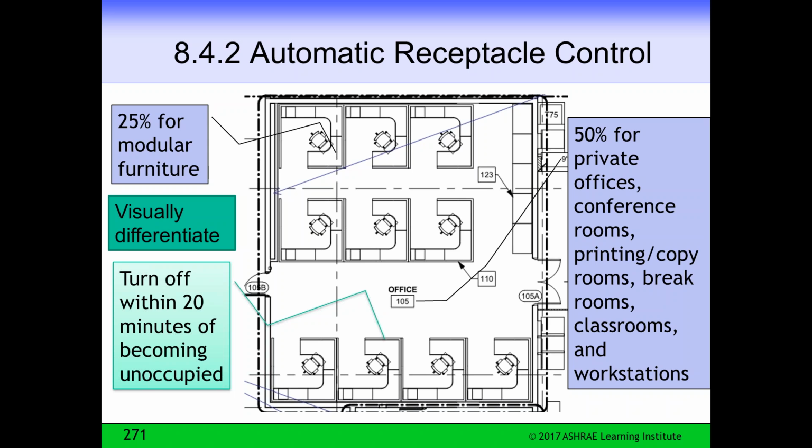Now, you can ask around, you can look at your own organization at night, with a building built to Appendix G standards, with the night setbacks and all the things we have in it. We would think that maybe 10% of the energy should be used when that building's unoccupied, no more than 20% for sure. But now we have all these 15-minute meters, and we can track how buildings operate throughout the 24-hour period. And buildings are running 50% and more of the energy when unoccupied than when occupied.